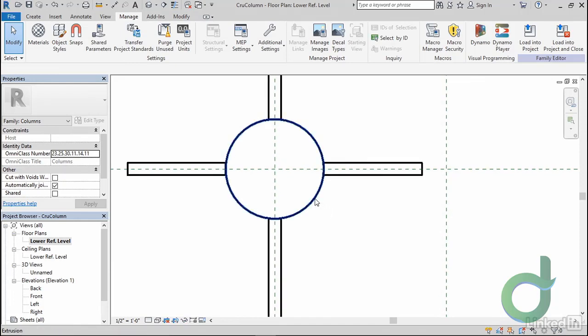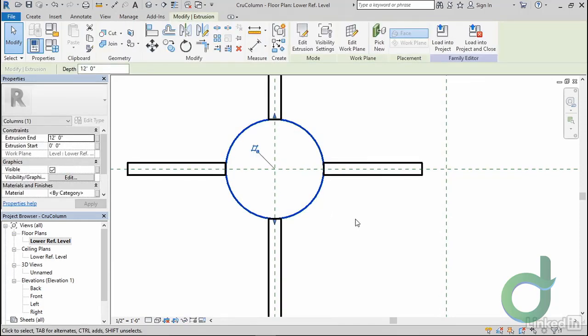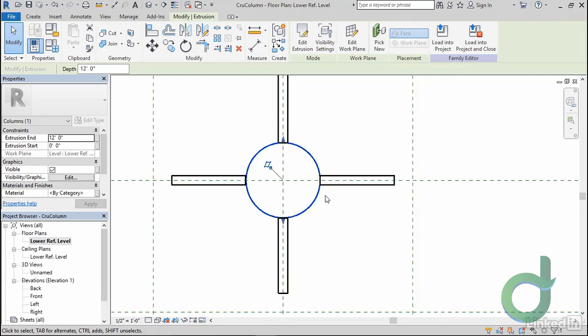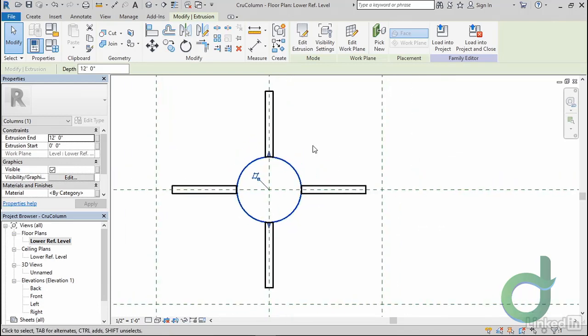I'm going to redraw the extrusion for the pipe here, using a polygon actually instead of a circle, to give me a flat spot to actually join on these boxes. Later in 3ds Max, I can smooth these columns if need be, and still have these exactly meet. Alternately, you could model this with extra lines and weld the vertices, but I have chosen to model this all in Revit, so I'm going to fix this column here in the family.